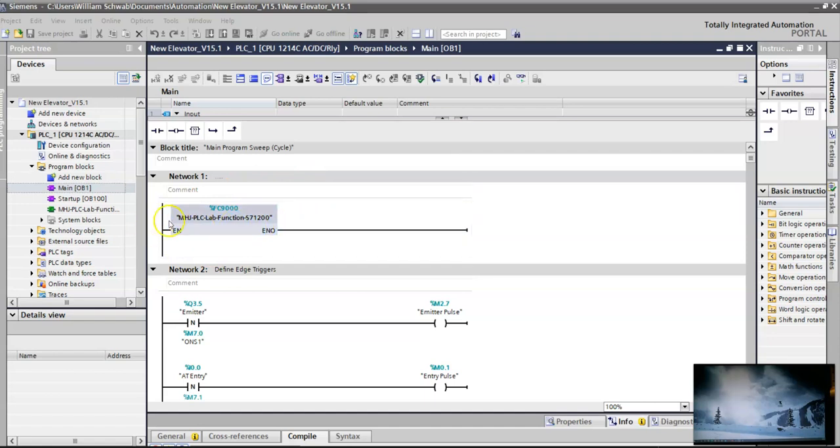You really don't have to do anything other than grab that function block, and they have a tutorial on how to work with the Siemens PLCs in general, but also how to set it up for the PLC Sim. You need this block if you want to run with PLC Sim. If you happen to have a PLC, you don't need this block.